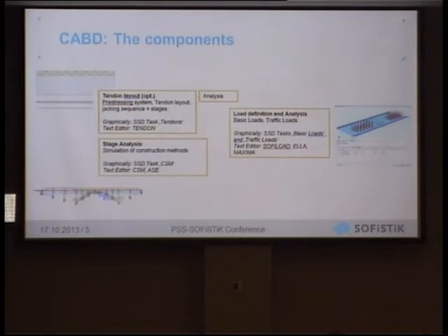After having the bridge model, so we might think about having supports, superstructure, and we have decided for maybe a shell model or a beam model. Then we should think about, if it's a reinforced or pre-stressed concrete bridge, to add the tendon layout or more than one tendon layout. So we can also relate the tendon geometry, like for example this simple parabolic or Girland-shaped tendons, to the bridge axis. So you don't have to think about any variations which are due to the curvature of the bridge. You just make this input on, so to speak, flat enrollment of the bridge.